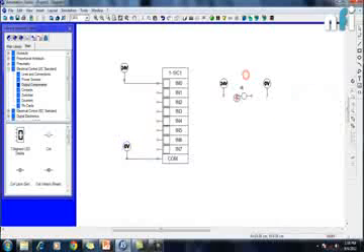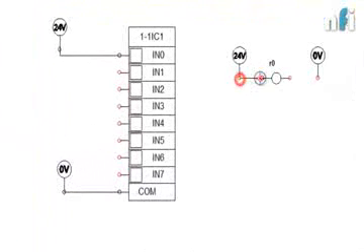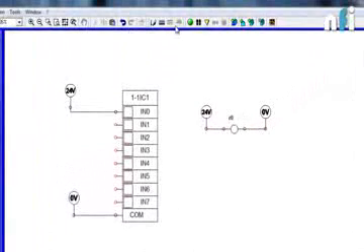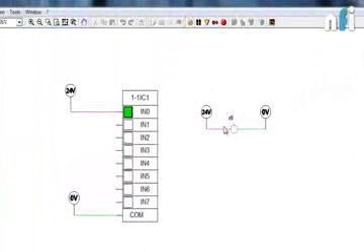Now this is my electromagnetic relay. What happens when I provide a signal of 24 and 0 across its two terminals? You will see it is on. In a similar way, these are the internal relays of a PLC. You need to provide a 24 volt potential difference across every element, every terminal, to make it on.